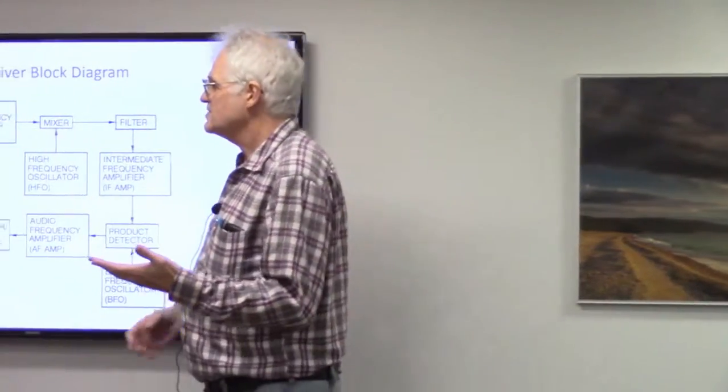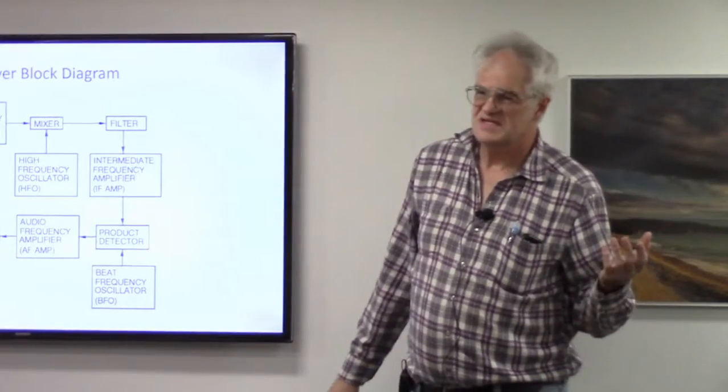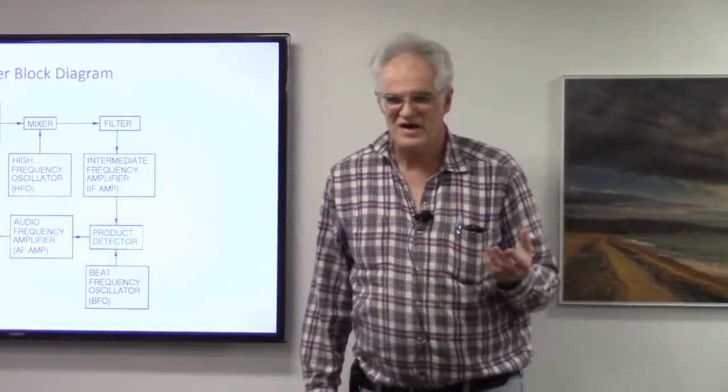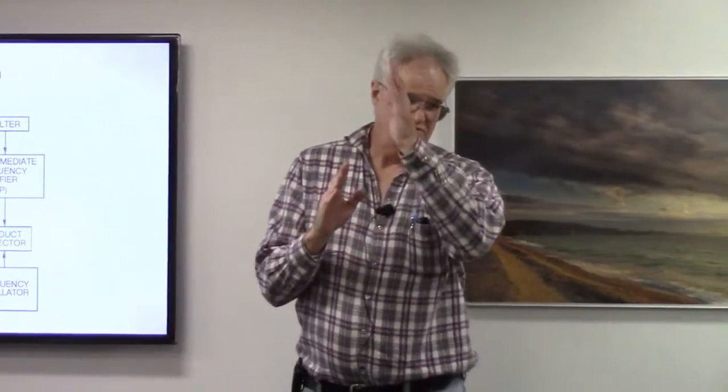For example, say we're working on a frequency of 7 megahertz, and our upper sideband would be from 7 megahertz plus up to 3 kilohertz. Our audio would be from 300 to 3000. So now we introduce our carrier at 7 megahertz and subtract the two.